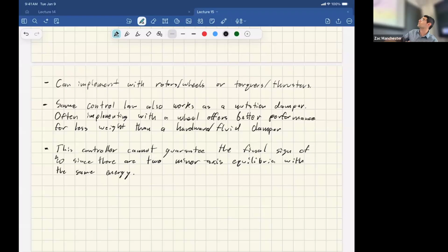So here's an example of it starting over here with a flat spin, and it winds its way out gradually and then crosses the intermediate separatrix and then heads towards the North Pole. And here's what the inputs look like. That smooth saturation gets you this behavior where it's doing bang-bang things when the errors are big. And when it gets close, it looks like a linear controller, which is what you want. So it doesn't thrash.